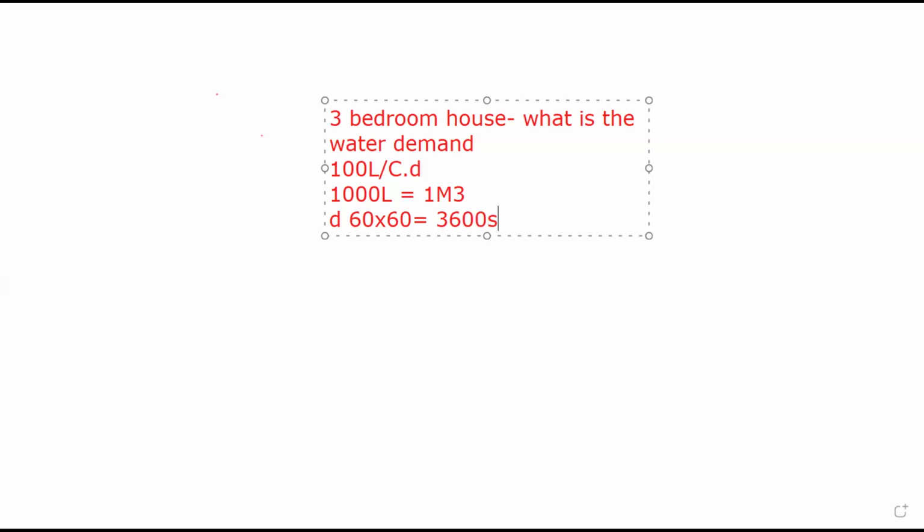In designing your pipe, remember our priority here is to calculate the pipe size. Is to get the water demand, and with the water demand, we get the pipe size. The water demand is known. We are using 100. Why we use 100 is that in one of the tests I have given us, you see how he broke it down. In a day, you require between 3 to 10 liters of water to drink. You require about 40 liters of water to wash. You require about 20 liters to cook food. You require about blah, blah, blah. It's all there. How you come about 100 or 120, whatever you choose to use. So that one is already established.